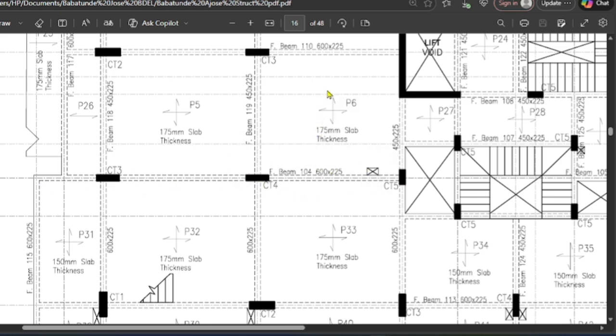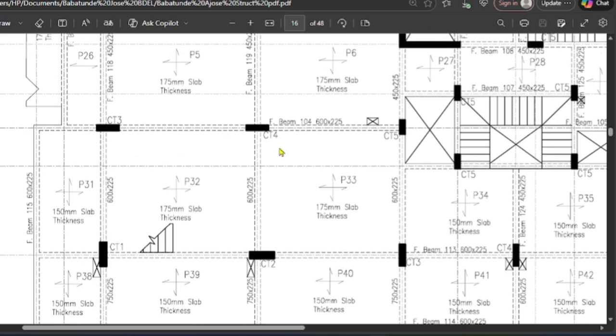When you are on site and you want to do this kind of job, you want to know how to arrange the reinforcement in that beam. The first thing you do is come to the layout of the drawing, because the layout is the beginning of every drawing. At this floor, we are at the first floor. The beginning of the first floor is the first floor layout. That's the first drawing you are going to see. You have seen the layout, where you have beam, where you have slab, where you don't have anything. Like this area, there is a void, you don't have anything there.